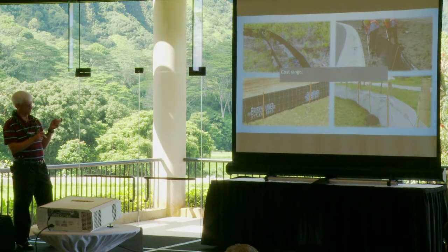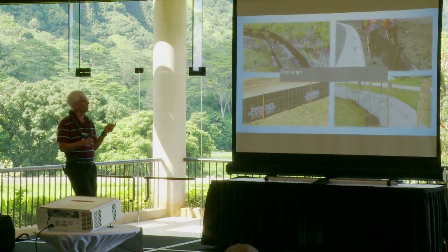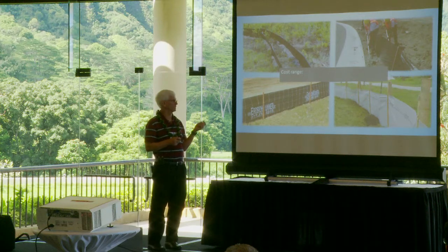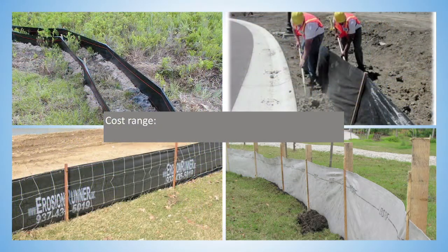There's also wire-back silt fence, and this one's a flexible silt fence called a BSRF, belted silt retention fence. It's high cost, but it outperforms a double row of standard silt fence. So you wouldn't put it everywhere, but if you had a low spot next to a wetland or an estuary that you wanted to make sure had maximum protection, this would be a device to consider. The posts are very strong. The material has little pieces of fiberglass impregnated in it, and it will expand, and it's capable of holding back clay. So that's a device for that.